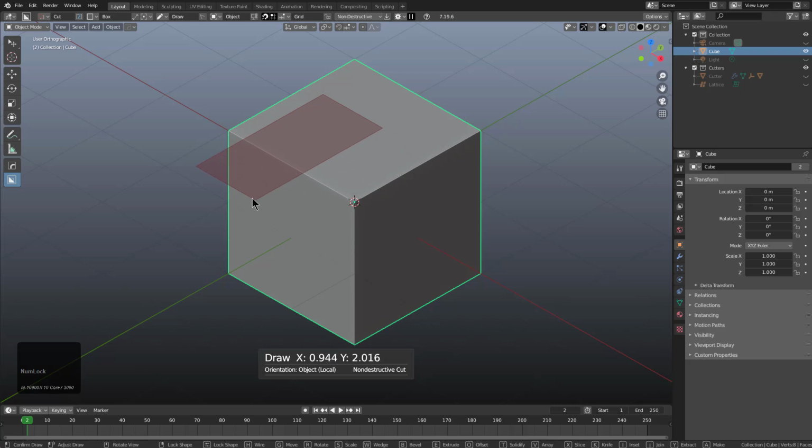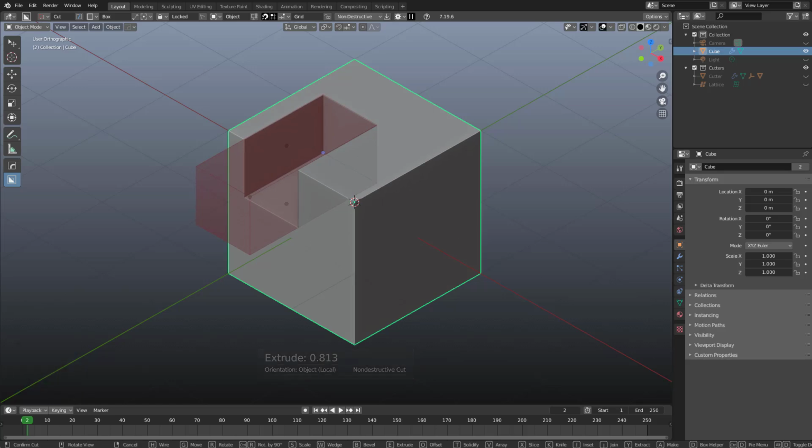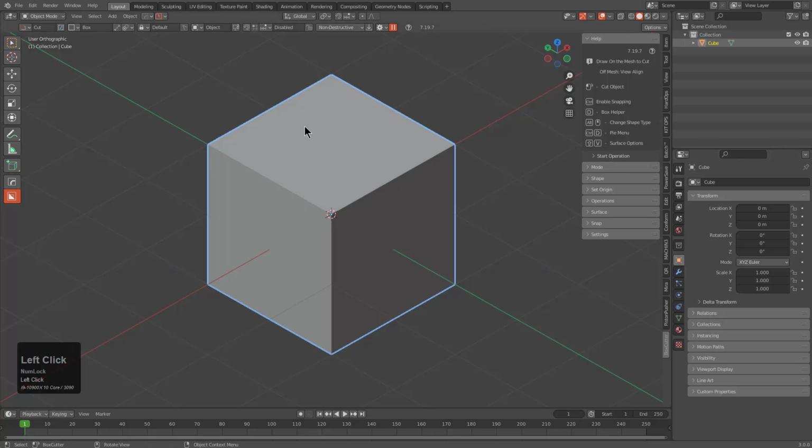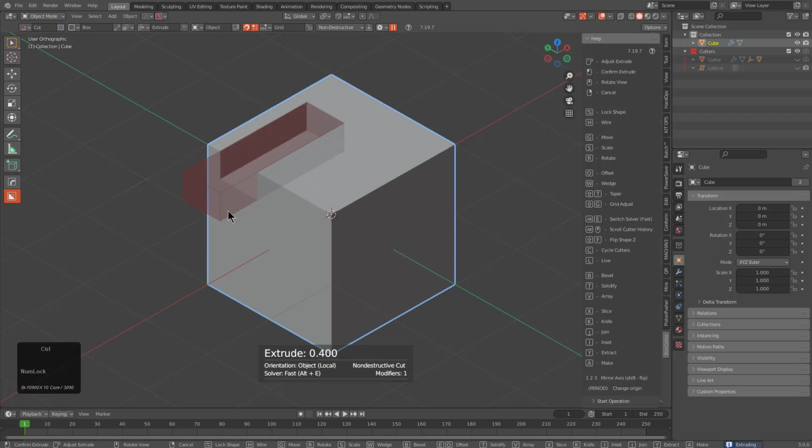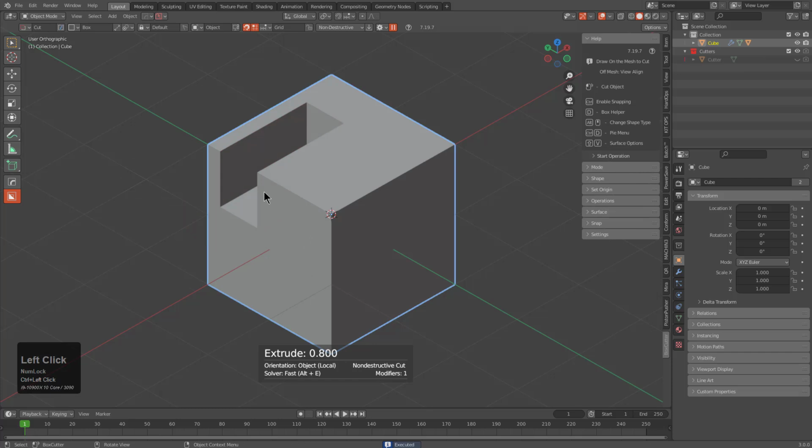And this is something that's just been kind of a long-standing issue, but it's something that definitely has been noticed by a lot of users. So I'm happy to announce that that issue has finally been resolved. Here we're in the latest version, 719.7, and we activate grid. And if we activate grid and we begin drawing, we can release Control. But if we press Control again, we see that the grid actually comes back and we're able to use the grid during the draw process in order to retain snapping in the event that we need it and then we don't need it. So now the draw is completed.